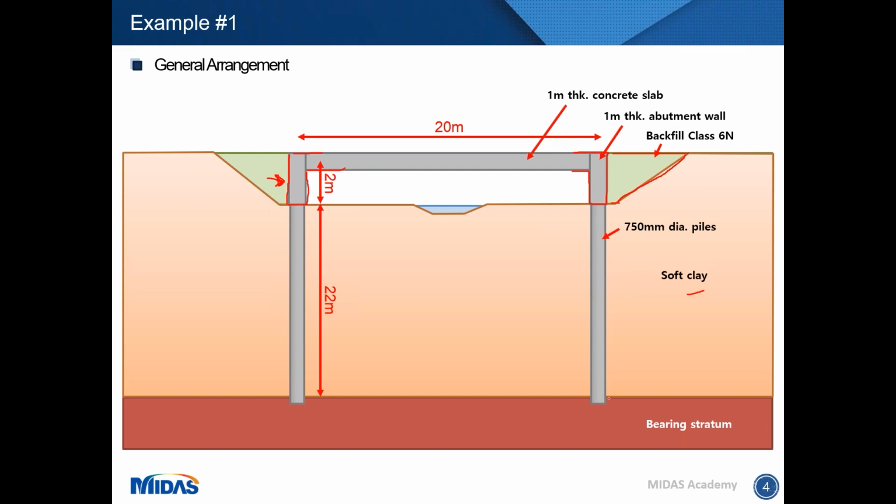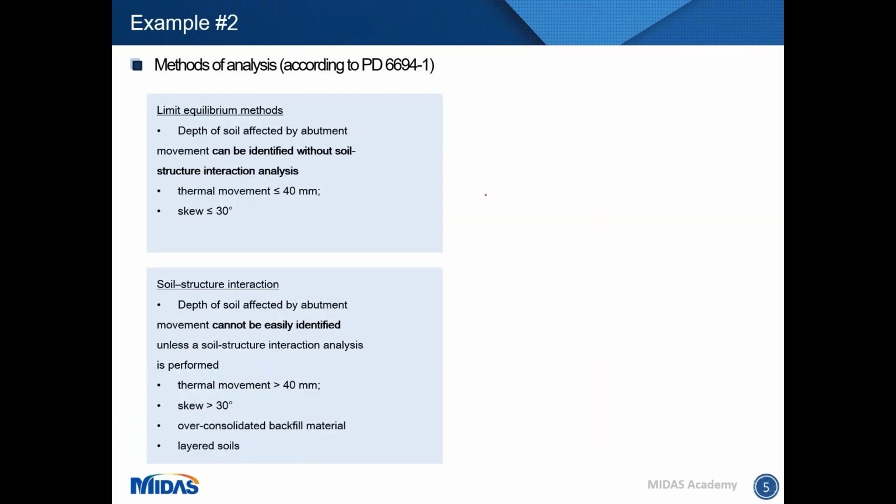So all the piles will not have any problems with ratcheting effects, it's going to be only the abutment wall. Since we have a very shallow abutment wall, our assumption is that we can identify the movement of this wall. We're going to assume that this is mainly translational, the kind of movement that we can expect from this top part of the bridge.